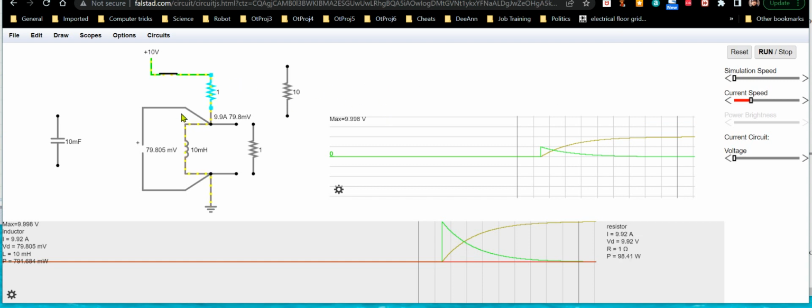You wouldn't expect a big resistor to make this time constant shorter. You'd expect it to be longer based on the capacitor, but it works just the opposite. Again, it's this duality between capacitors and inductors that causes a lot of this, and that's why it's important to have an intuitive understanding of some of these things.